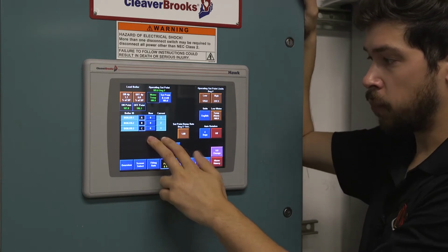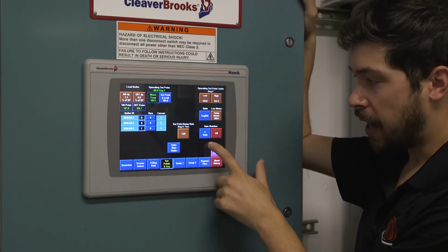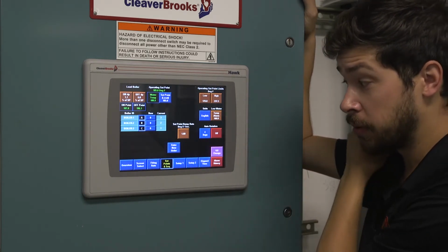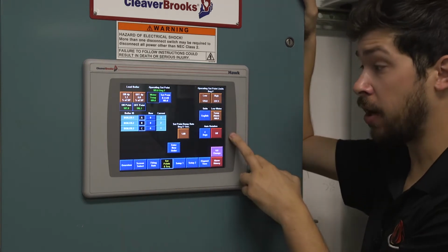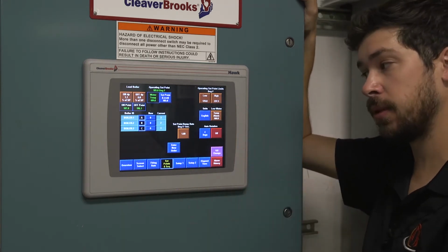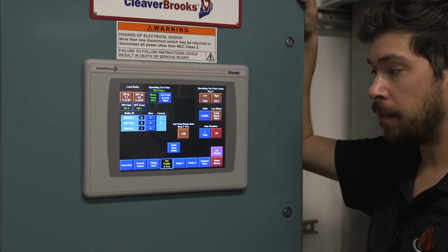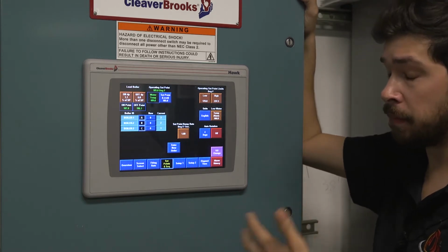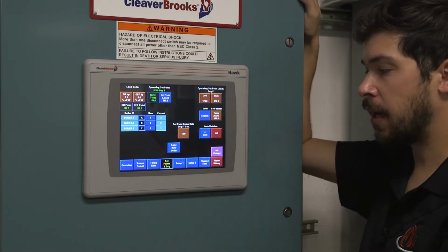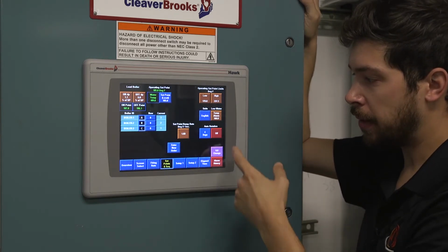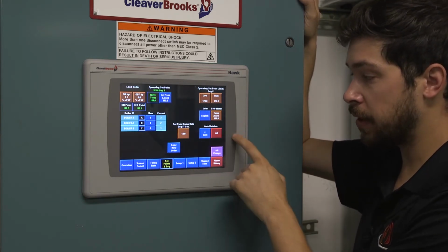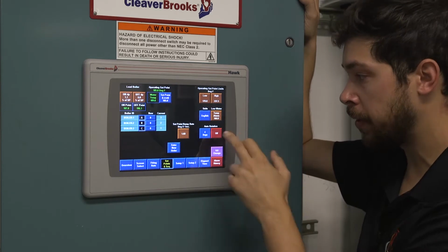This order will automatically change as per the auto rotation schedule, which is apparently currently off, probably just due to the fact that boilers 2 and 3 were not running for an extended period of time due to the gas issues. This would be a good thing to turn on for the long term.